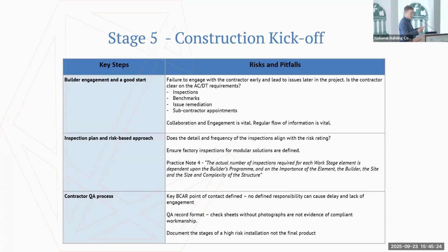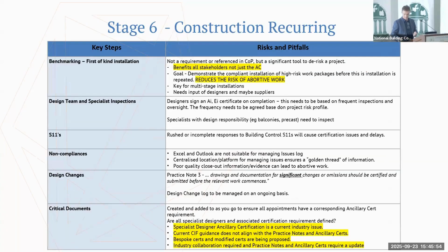You need to see evidence of the first fix with the gaps in place, with all your screw fixings to the side. Your second fix will be your drop seals and your ironmongery and intumescent pads if they're there. Your threshold gaps. So there's multiple stages to various installations, and it's important that the inspections that are uploaded align with that as best you can. Same with fire dampers. There are things that are not done in one go, and therefore the inspection should align with the stages of the installation.